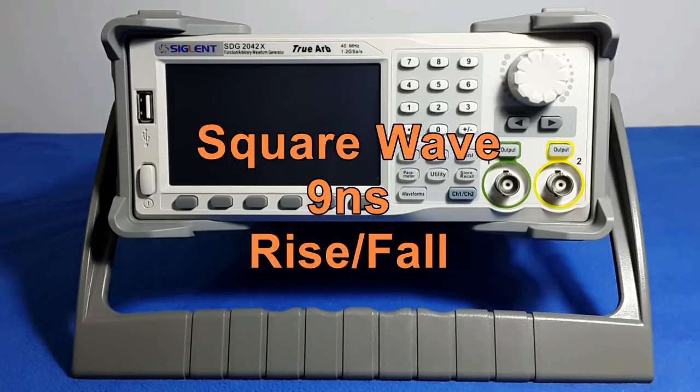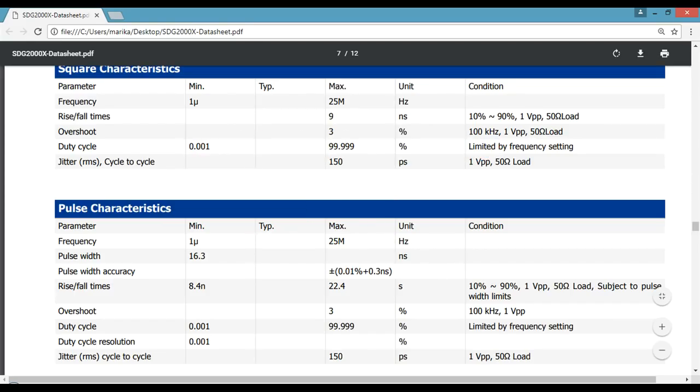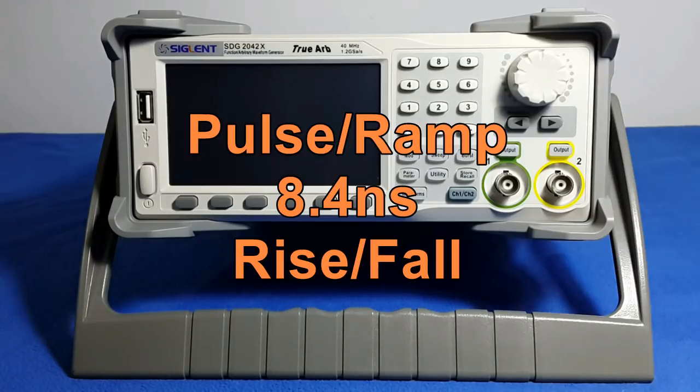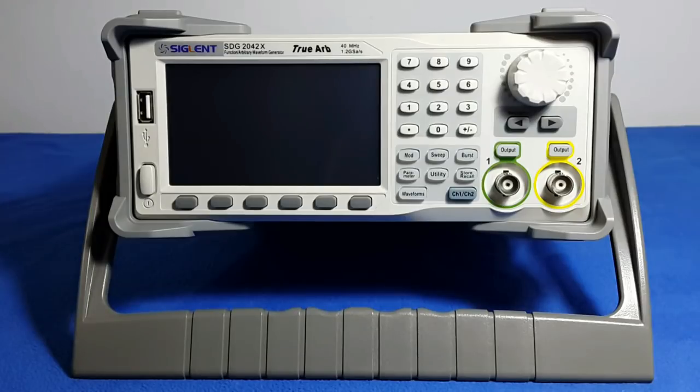And for the square wave, it is 9 nanoseconds the rise and falling times. It could be even less than that. For the pulse or the ramp, the minimum timing is rising in 8.4 nanoseconds and the maximum could be 22.4. What I am not expecting here, I'm expecting just the minimum. Let's take a look at the hardware and later we will check these signals.